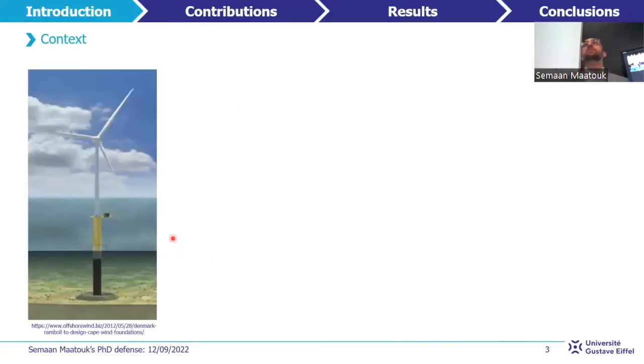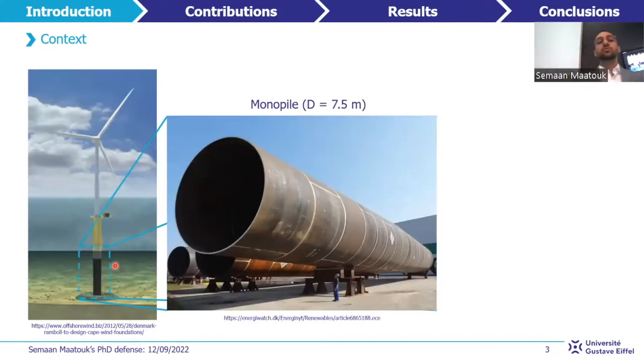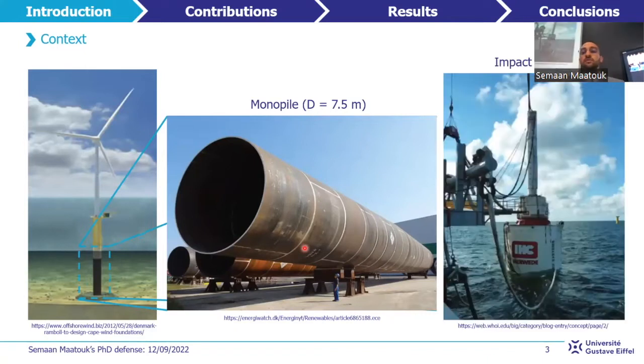The marine renewable energy in France and around the world brings new challenges. One of them concerns fixed wind turbines, which offer an economical solution when the seabed is beneath 35 meters. Generally, monopiles are today the preferred foundation solution for offshore wind turbines. These monopiles are single, hollow steel tubes with a multi-metric diameter, often installed into the seabed by impact driving, using a hammer that taps on the monopile in order to drive it into the ground.